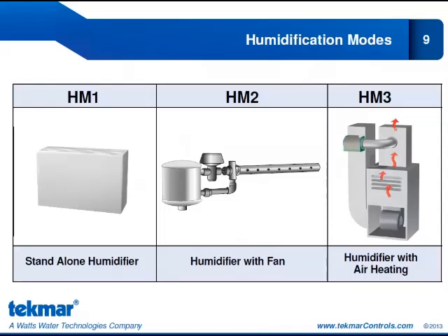There are 3 humidification modes in the 553. These are the same modes that are in the 557. Humidification mode 1 will enable a standalone humidifier. So this is a piece of equipment that is not in the ductwork.